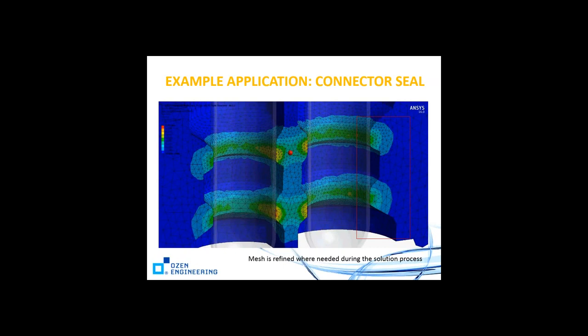It remeshes it, and as you see, it's still a coarse mesh. It's not a really fine mesh, but you still get a solution. Is it doing the remesh between load steps? Yes, between load steps. It stops itself, remeshes, and continues on from where it left off. So this is really a nice procedure for FEA. This procedure did exist in ANSYS Classic, but for the first time in version 16, it's being revealed in Workbench as well.